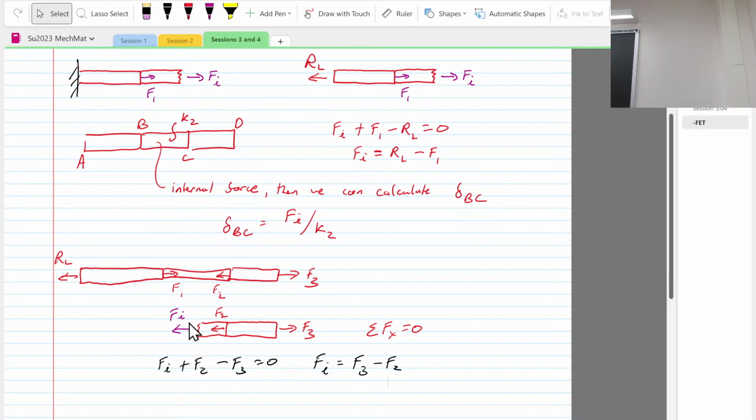The second or third member is stretching, when it thinks about its deformation. All it cares about, in terms of its elongation, is what is the internal force on it? And as we just discussed, no matter what I change that third member to have for a stringiness, it still transfers the same amount of force throughout.